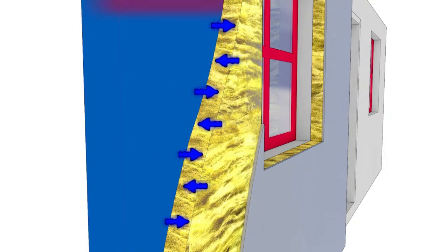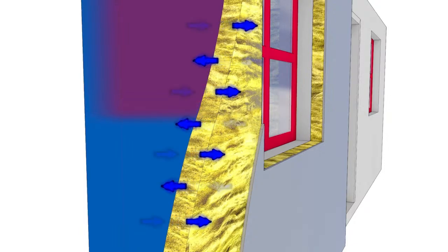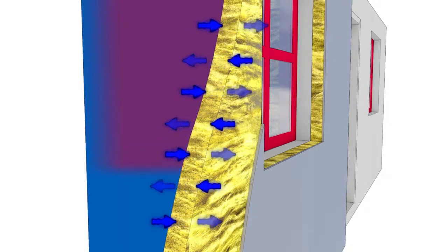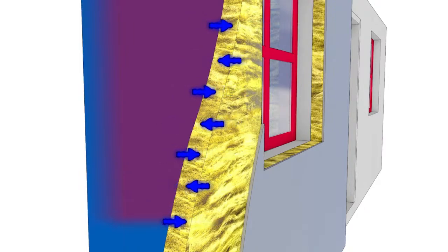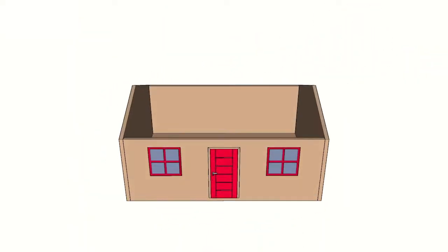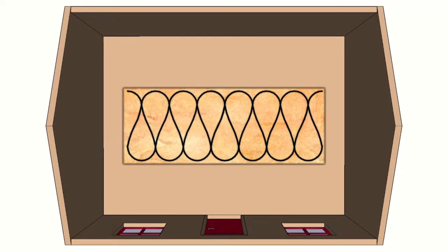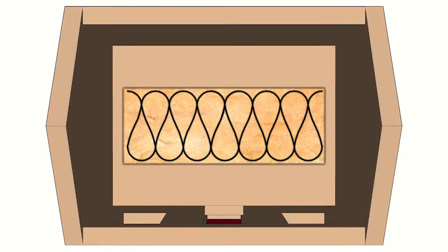Permeable insulation prevents moisture being trapped in the construction and does not disrupt the established balance of moisture flows within the building fabric to the same degree. However, traditional types of moisture vapour permeable insulation, such as mineral fibre, tend to be very bulky. This leads on to the second challenge in historical refurbishment, preserving interior space. While mineral fibre or natural wool do a good job ensuring moisture can permeate, their relatively high thermal conductivity means achieving modern thermal standards can require up to 200 mm of thickness, which is not always practical to incorporate into an existing space.